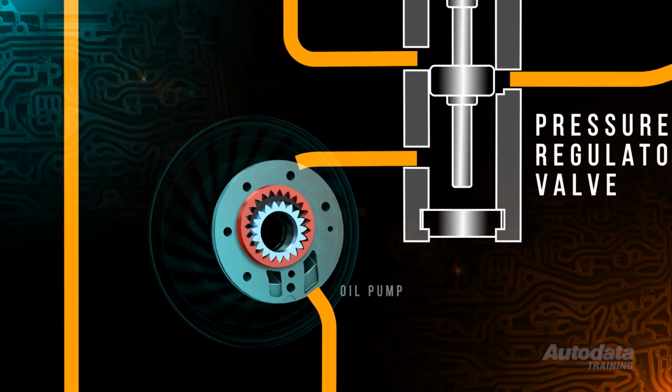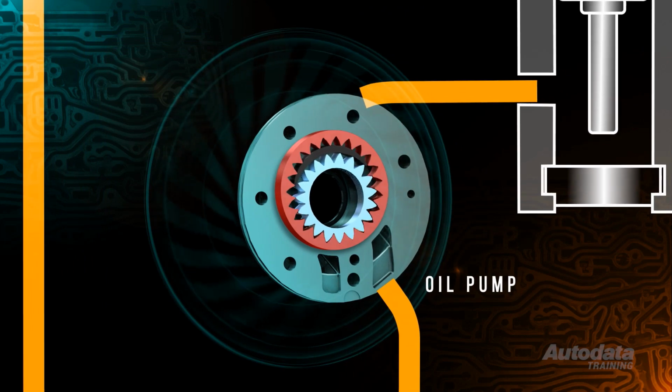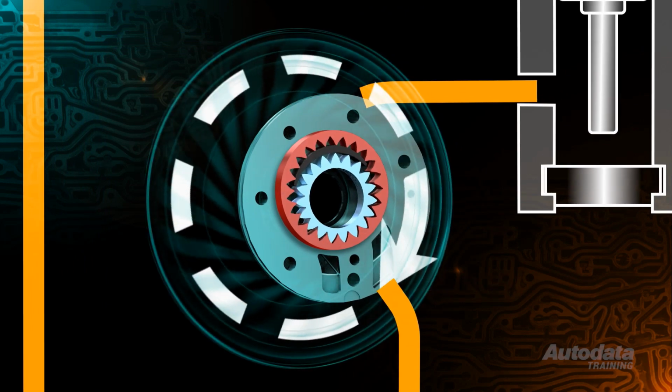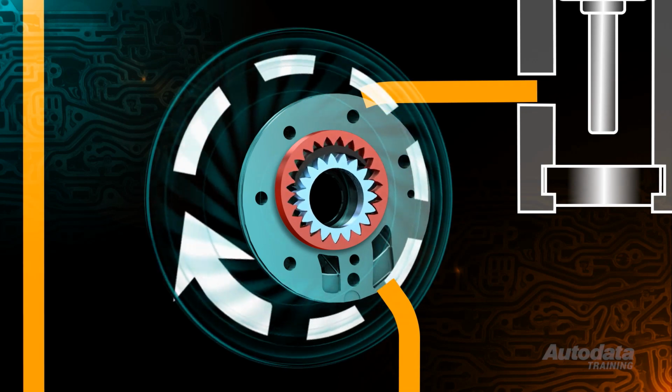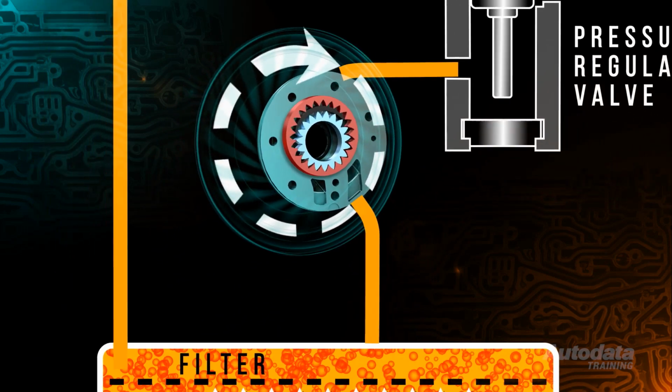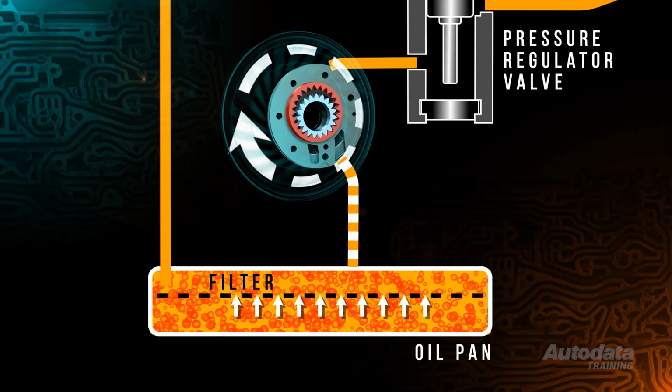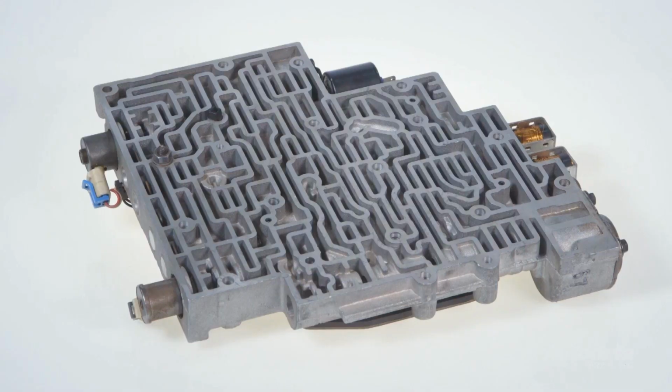A fluid pump is responsible for producing flow within an automatic transmission. It's generally mounted in the front housing and driven by the torque converter when the engine is operating. Fluid is drawn from the pan and through a filter before commencing its journey to the pump. Transmission fluid is pushed from the pump to the valve body for operational control and rotating components for lubrication.